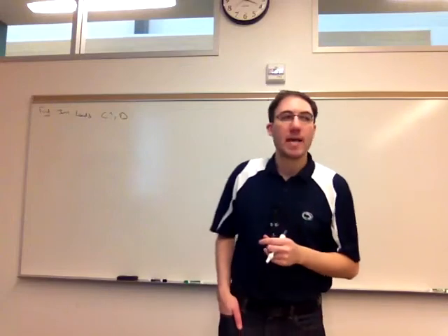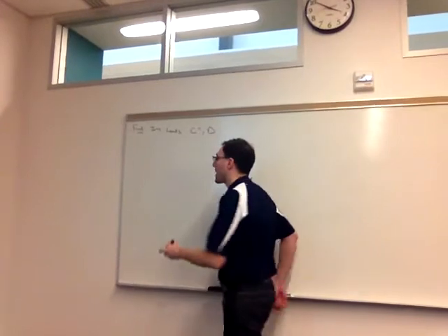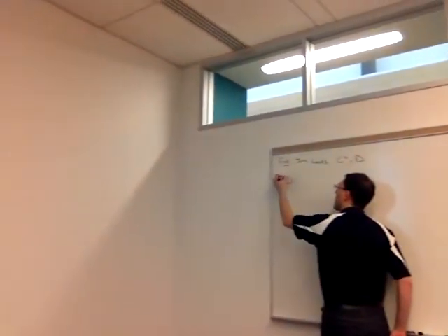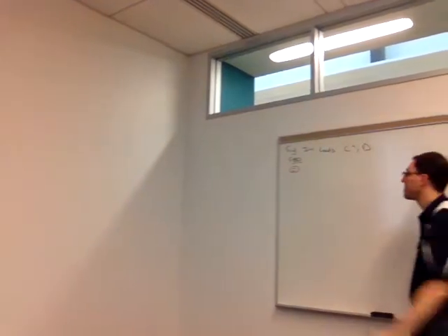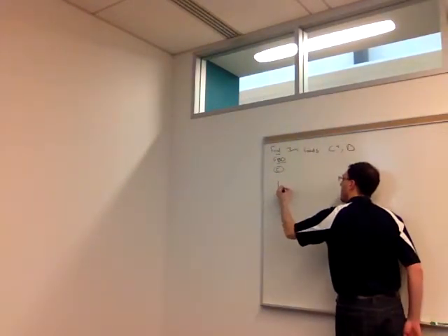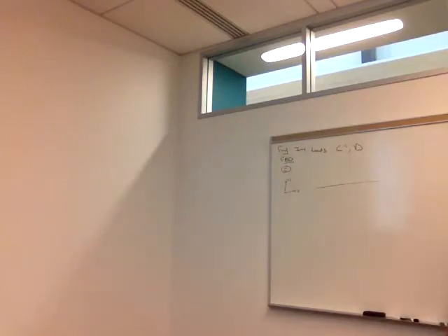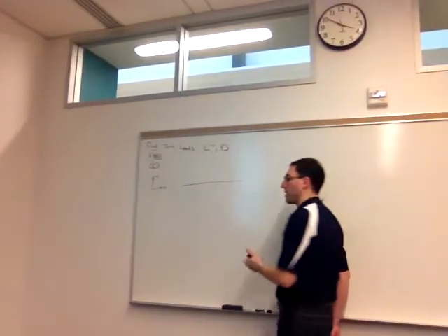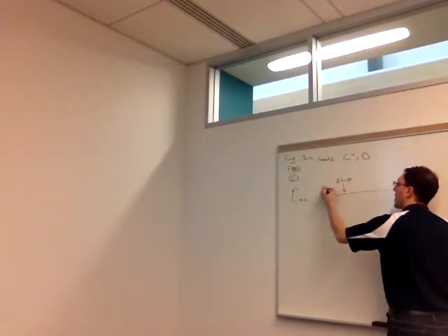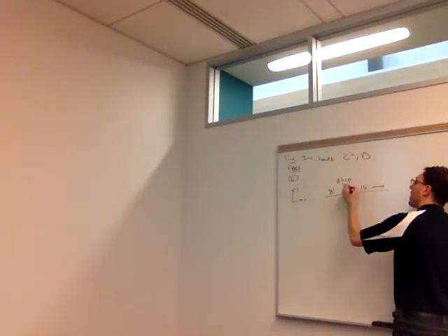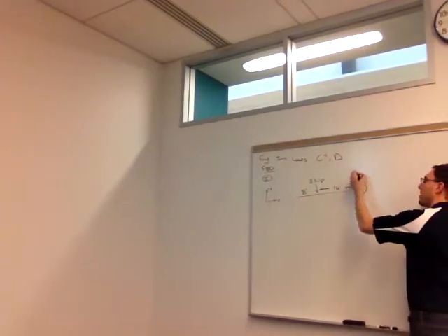Looking at the beam, it's statically determinate, so we're going to start by finding what the external reactions are, just like we would in Chapter 5. We have an external point load of 8 kip. We have an applied moment or applied couple of 40 kip feet.